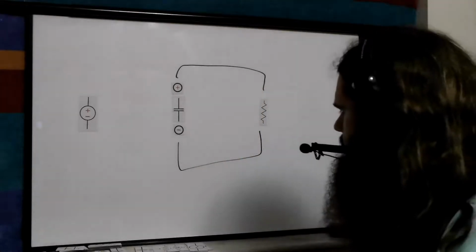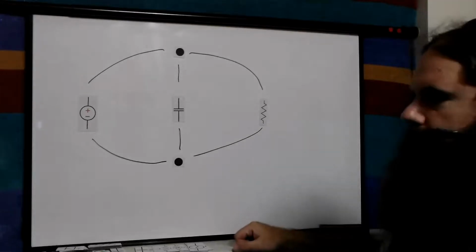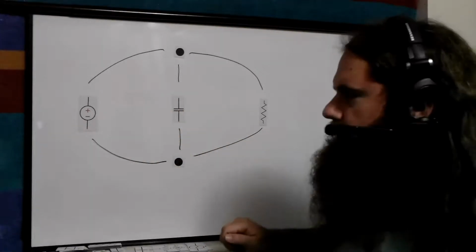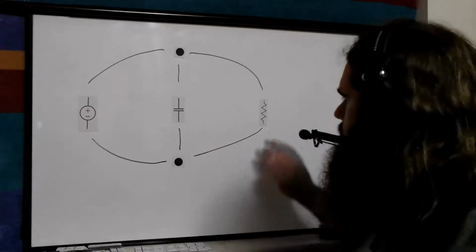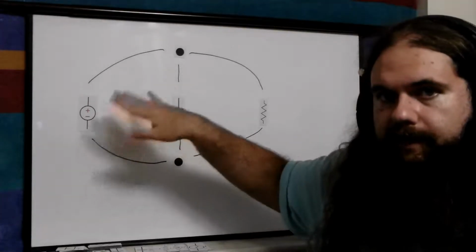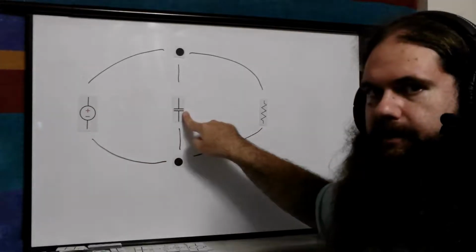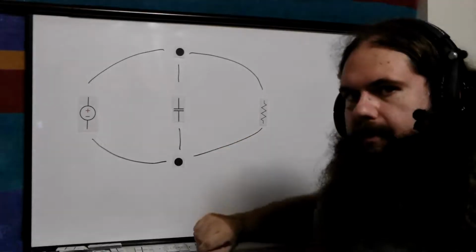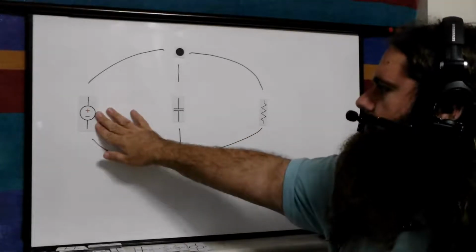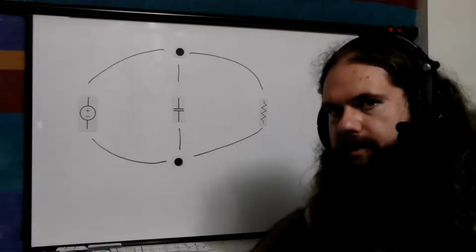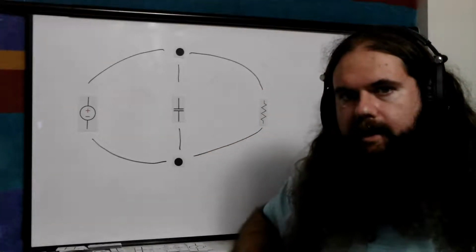Now what if we do this? What if we connect them in parallel? Well, let's assume I just did this. I just connected the power supply, I just flipped the switch. The capacitor is uncharged. Nothing is flowing through the resistor. The electric field is establishing itself. So the first thing that happens is this capacitor greedily sucks up the power it can. So you have this positive charge, this negative charge here, is basically going into charging the capacitor. And the resistor is getting almost nothing.